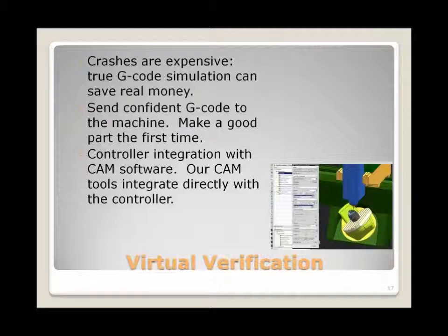It's definitely important that you don't have your spindle clearance off, thinking your cutter's long enough, but once you tilt the table, you don't have as much clearance as you thought you might have. So here we're looking at, as John said, an articulated table, and it's important to have a CAM solution that can simulate your different types of machines.